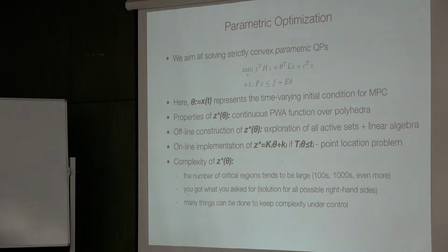Then you think twice whether going the analytical direction was the best one. Really, the analytical solution is usually applied when you have no other option. No other option could mean that you have nanoseconds to compute your control action, for instance, where even the best online algorithms wouldn't work. They work in the microsecond range, something like that. If you have nanoseconds, you cannot allow any complex algebra. There you are really limited to comparisons, additions, multiplications, and that's it.